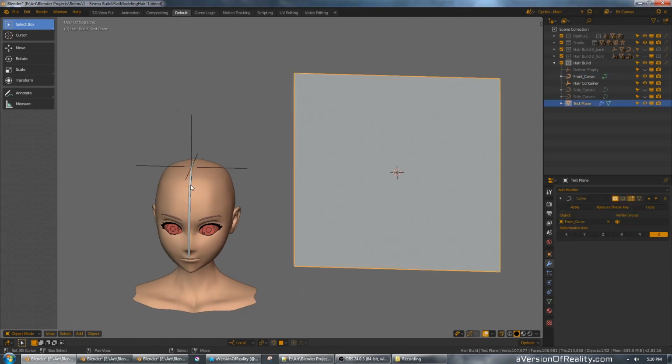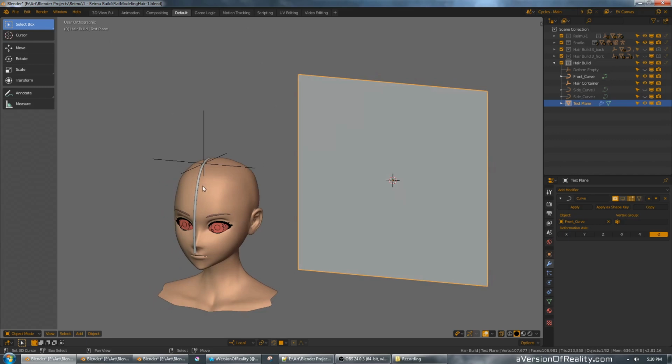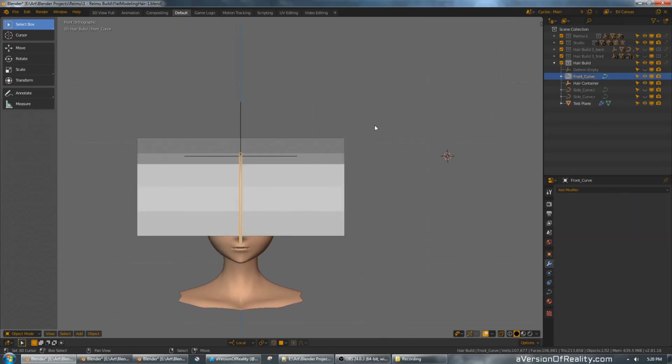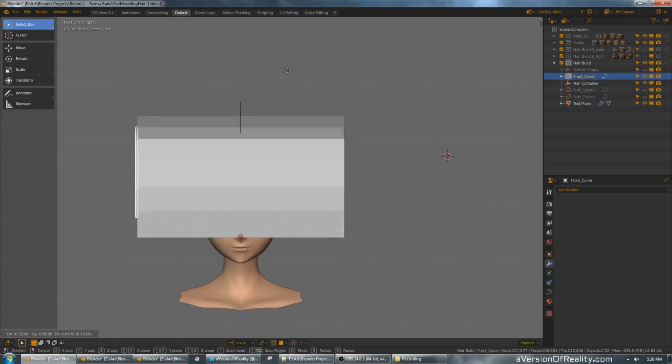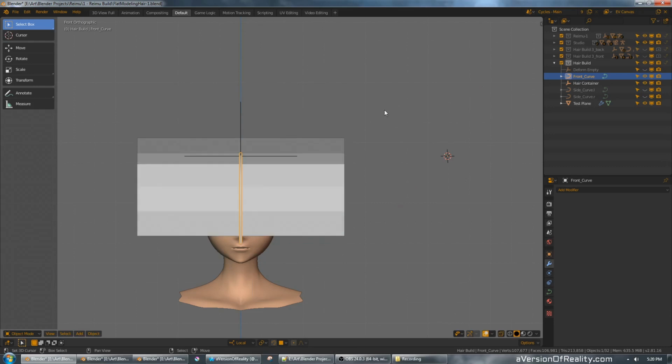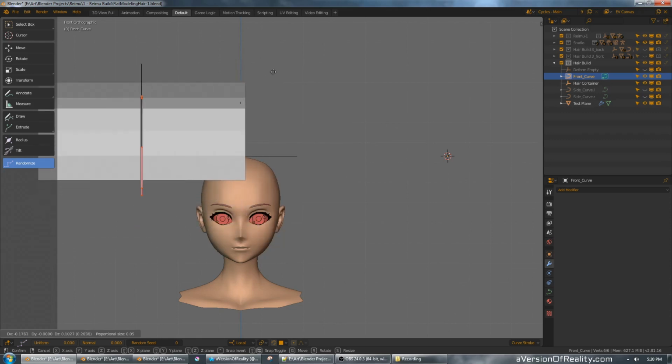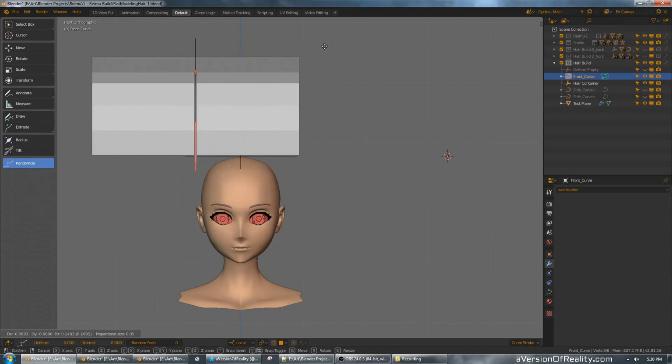And you have to keep those origin points lined up, because that's what is used to define how far the curve moves. If we re-enable the curve modifier, and then move the curve in object mode, it messes things up because it's disaligning their origin points. But if we move it in edit mode, the mesh stays properly on the curve because it's keeping a consistent offset.